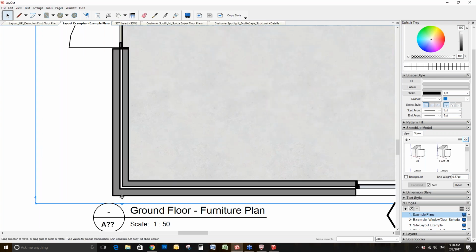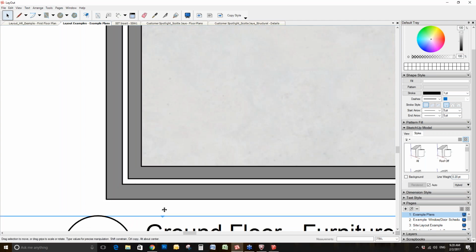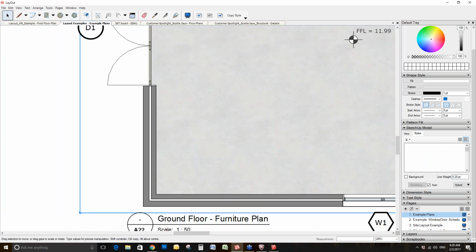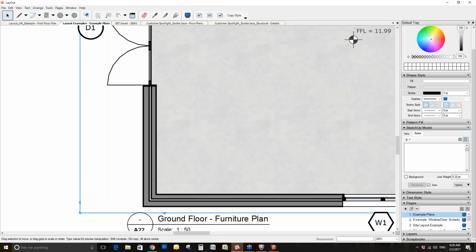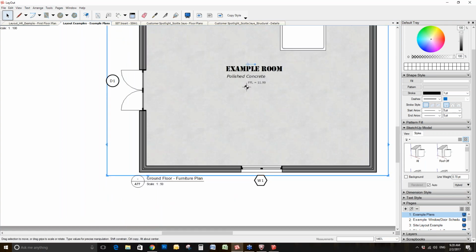And once that updates, you're going to see that it's going to go a lot thicker. I actually did 5.7 there. Let's do an actual 7. There we go. And if I go lighter, still a 0.2, you can see that it's going to lighten your overall drawing. So you've got an overall control of your sections and your overall line weight thicknesses in your model.